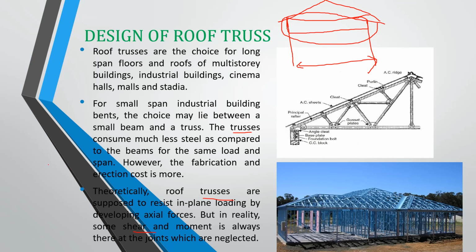What we learned in our structural courses is that if this is a truss member, a triangular truss composed of three elements, and suppose that a gravity load, or a load in the vertical direction downwards, is acting at this joint, then if we suppose that these two joints are restrained here, under the influence of this vertical load, this joint moves downwards, whereas these two joints on the left and right move outwards, somewhat like this.